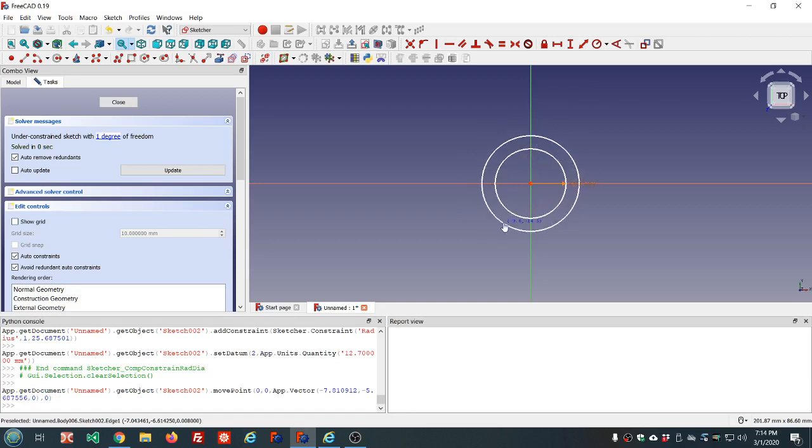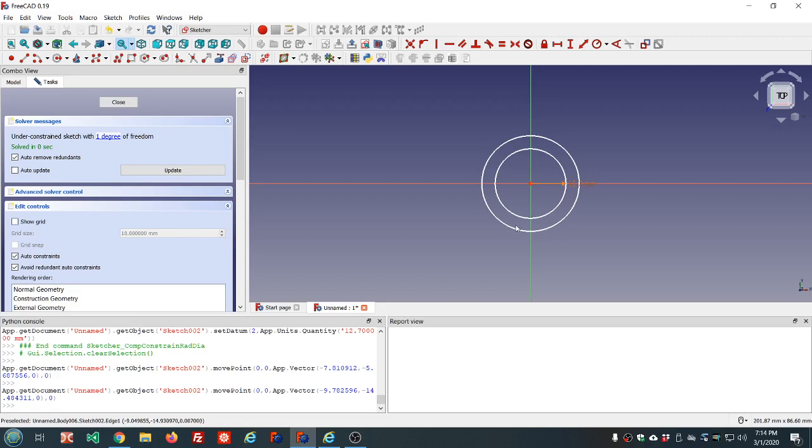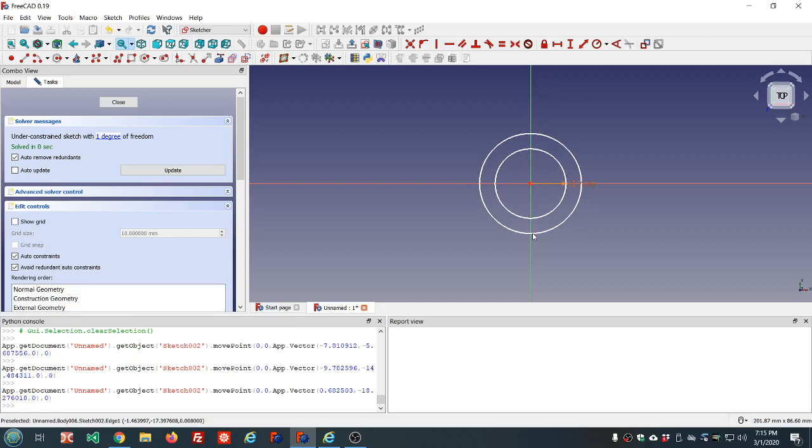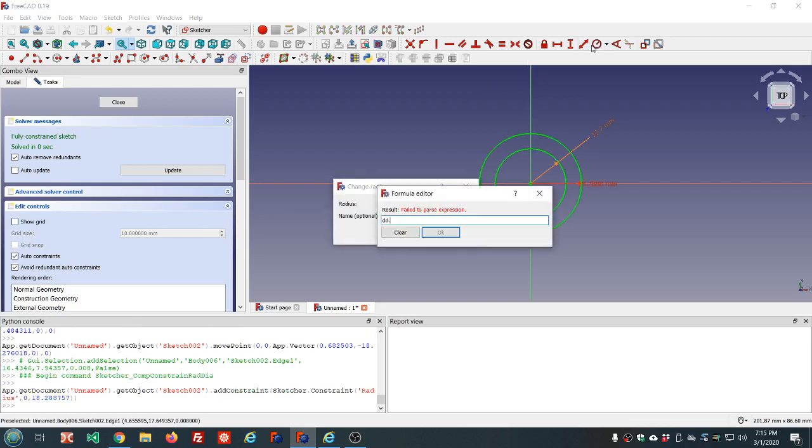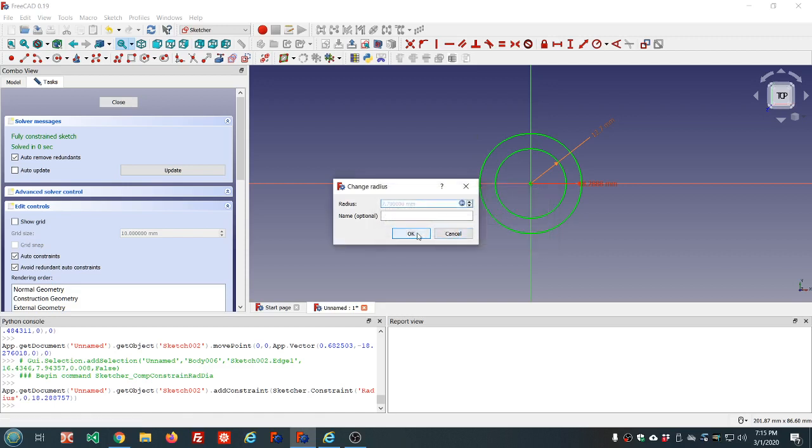Now one thing to look out for when using this loft tool is that the order of creation of your circles is important. The order of creation. If you make the first one outside and the first one inside, they're going to cross and you'll end up with a self-intersection. So if that happens here, I know what to do to fix it. And this will be the internal one. So that's outer radius minus wall thickness. There's about a 50-50 chance we're going to run into that issue.